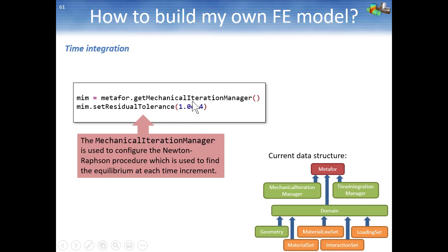So if you have a perfect value, you would like this difference to be 0, because you want a perfect equilibrium, but numerically you will never reach 0. So the balance between the internal stresses and the forces generated from these internal stresses and the external forces, the difference will be close to 0, but never 0.